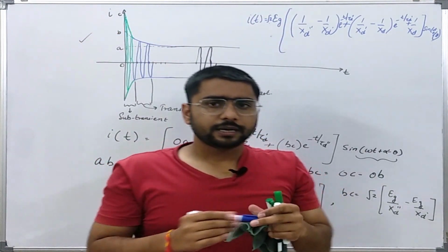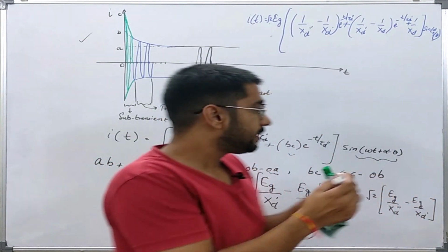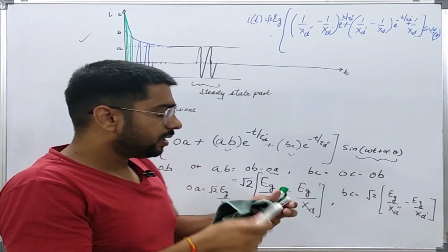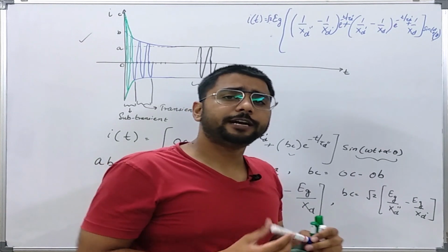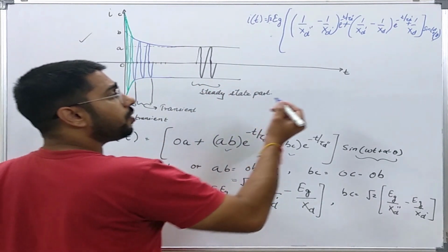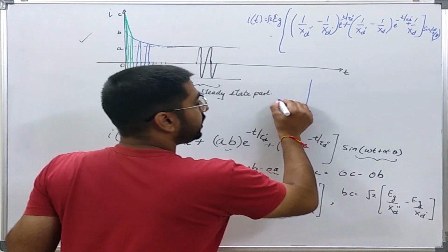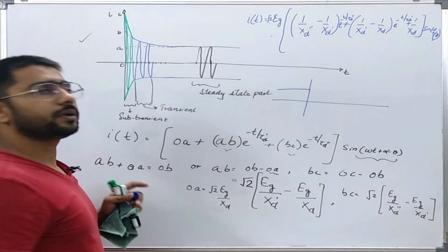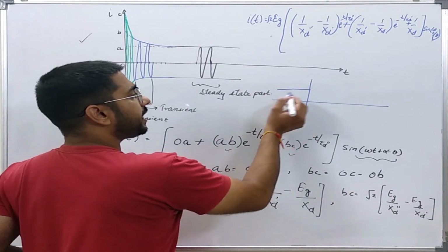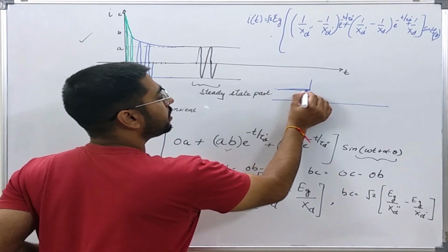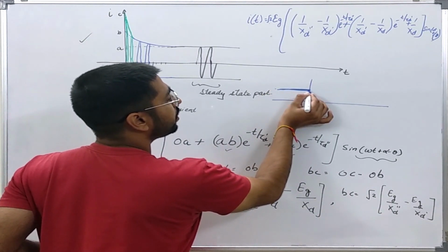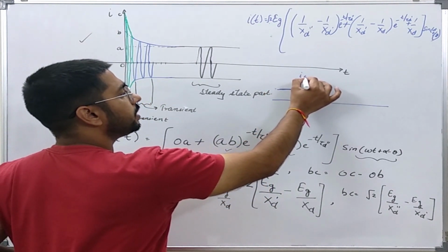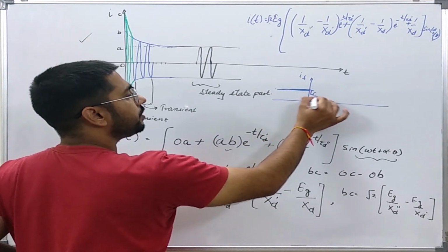Now I have told that there will be induced currents in the field winding and the damper winding. So what kind of waveform can we expect in the field winding? As we all know, the field winding carries a DC current. So before this short circuit happens, let us say this is the DC current, a steady, constant value in the field winding at some value IF naught.